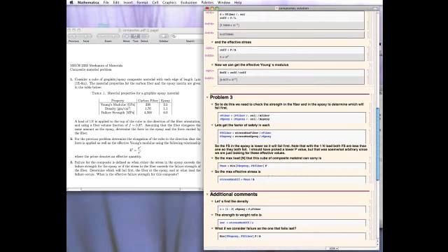All right, the final problem wants you to determine the strength, okay? And there's two ways to consider the strength. The first type of definition is, well, obviously, the fiber and the epoxy will fail at different loads. Typically what will happen is you'll pull, the epoxy will start to fail, and then the fiber will fail. Now, do you want to define failure as the fiber failing? That would be the less conservative, or as the epoxy first starting to fail. That would be the more conservative. Usually it's somewhere in between.